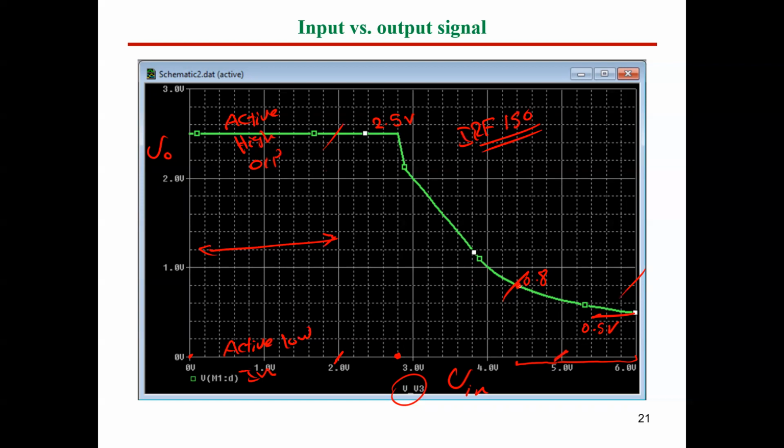So we can say now our range of active high signal when we apply to this circuit would be, for instance, from 4.4 volt to 5 volt, like that. And we are sure when we apply the active high signal 4.4 to 5, the output would be active low, which is going to be from 0.8 volt, even less, to 0.6 volt, like that.